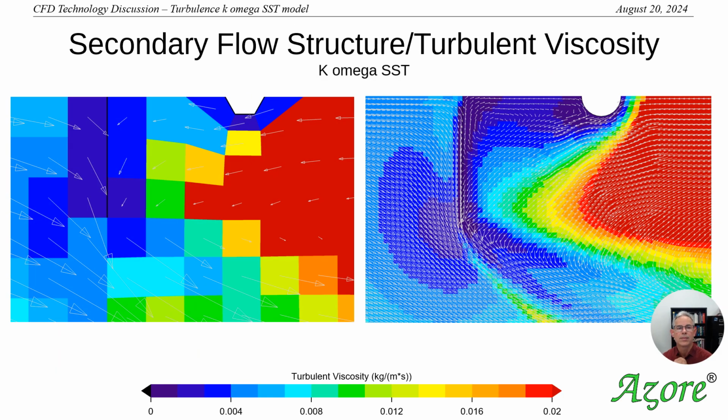So now let's look at the secondary flow structures. Here, on the left-hand side, we're looking very closely right around this plate and the pipe, and you can see that the pipe is resolved more closely in the fine mesh structure, whereas in the coarse mesh structure it is segmented, which is just a product of the mesh length scale that we chose. What I've shown here also is it's not smooth contours.